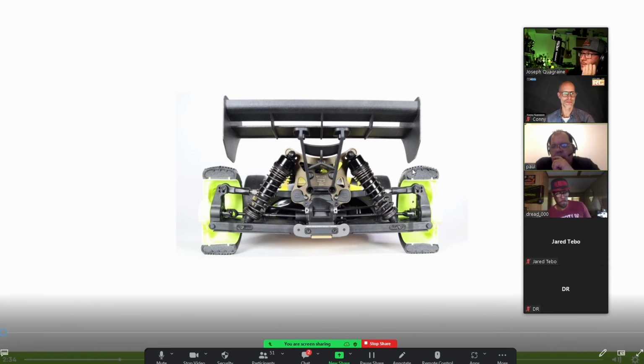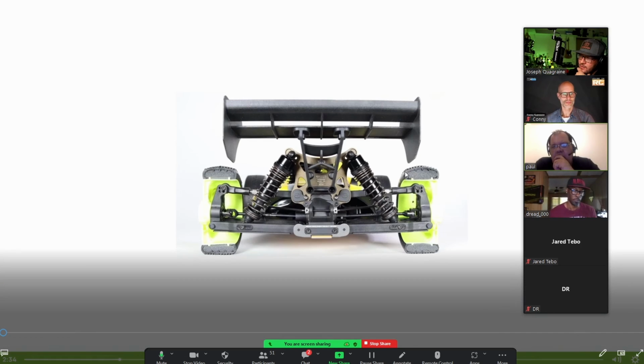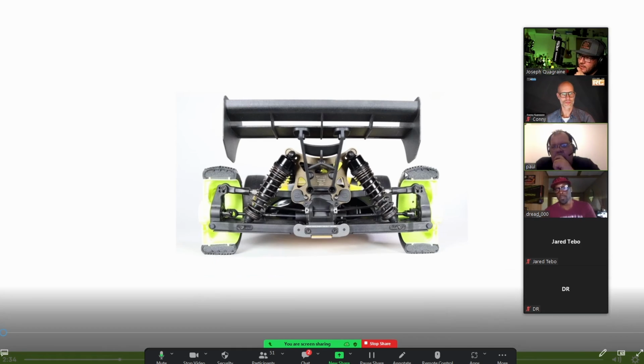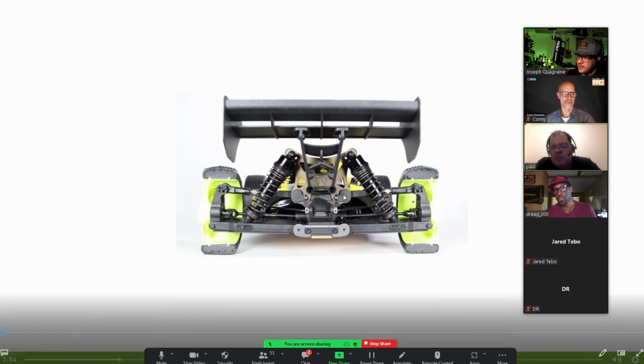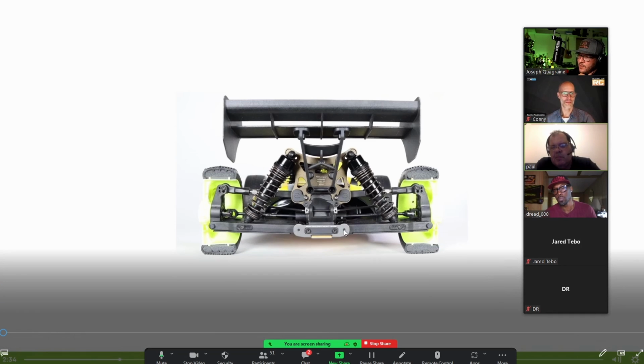Well, that's why I say that car setup is an art and not an exact science. Yeah, I get it. The way I would do it is, like I said, for the lower arm, I think about it as support, and then in or on the track, I adjust it with the upper link. So it's like you said, if you run the lower arm higher and then you also raise the upper link, you can have a car that is clearly in the track, yet it still has support from the lower arm, so it's not too soft and collapsing on the rear end when you accelerate.